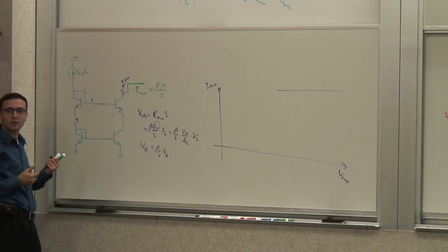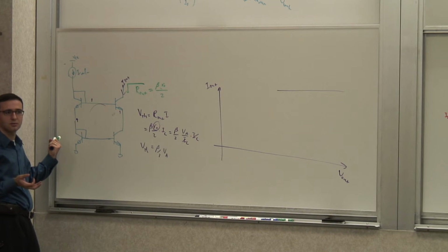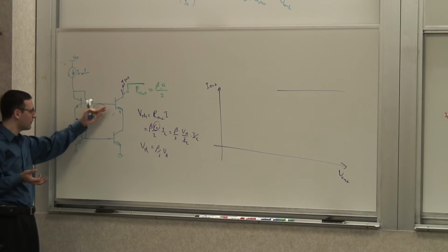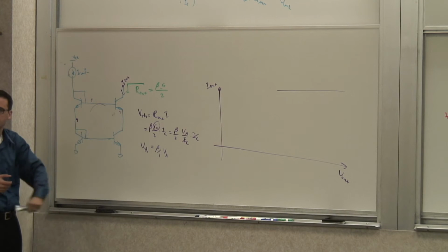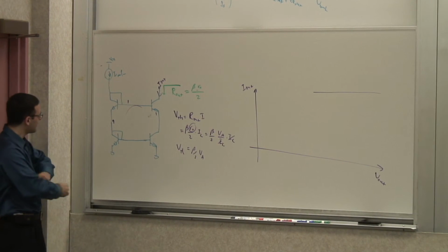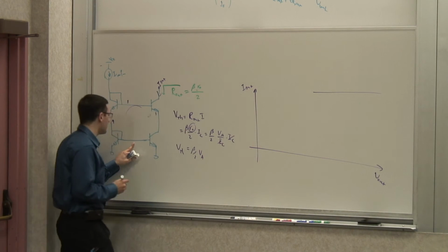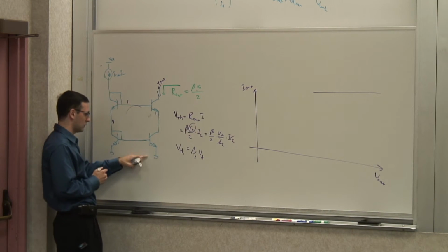Well, I have to find out when one of the transistors goes into saturation. Right? These guys can't go into saturation. These guys can never saturate. So it's one of these two. The question is which one goes into saturation first? How do you determine that? Well, let's look at the DC levels. Nominal DC level. What is the DC level here, approximately, with respect to ground?